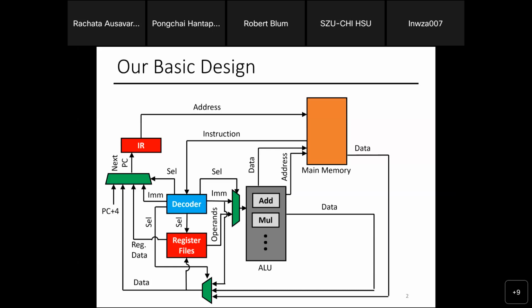With multi-cycle architecture, you can stage it: the first cycle just fetches, the second cycle just decodes, the third cycle does the first part of the add, and the next maybe handles the upper bits. Let's say you add 64 bits; it might take a few cycles, right?